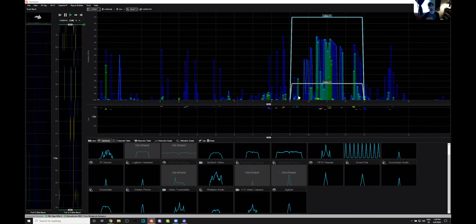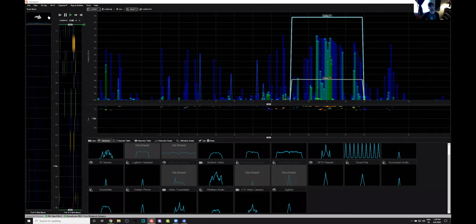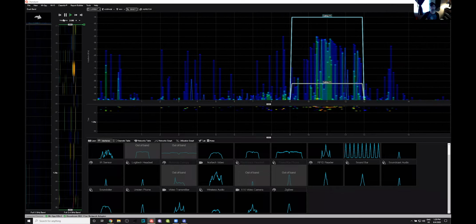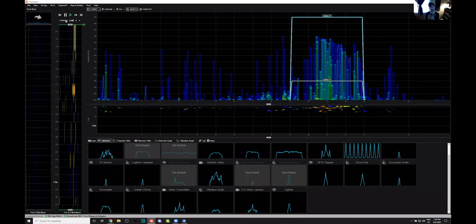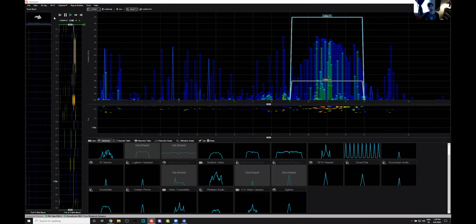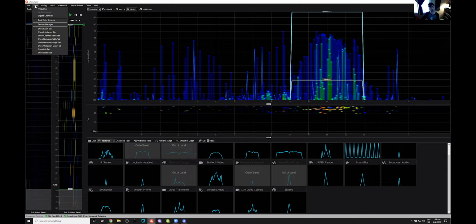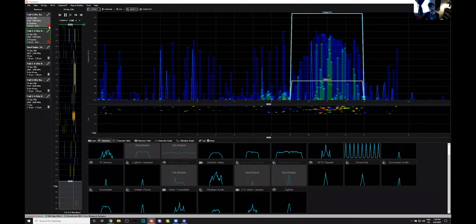And so right now we started a new session. I just removed that source of interference, and I want to bring up how sessions work in Channelizer. Once we went into that device finder, it focused the resources on such a small portion of the spectrum that it no longer was sweeping around it. And so to go back to those sessions, you just go to View and Session Manager.